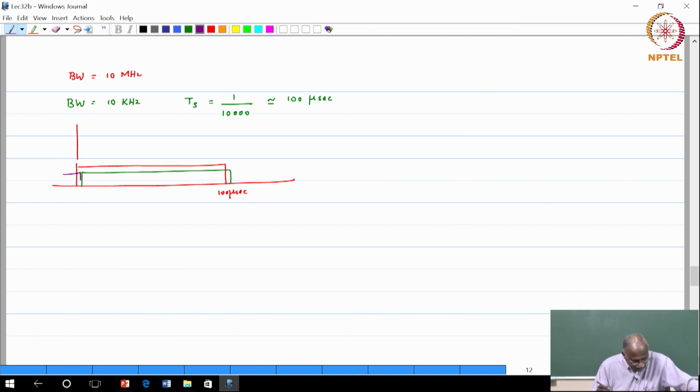As we mentioned yesterday, if your RMS delay spread sigma tau is less than 1/10 of the symbol duration, that is 0.1 times the symbol duration, then you can more or less say that the channel is considered flat.